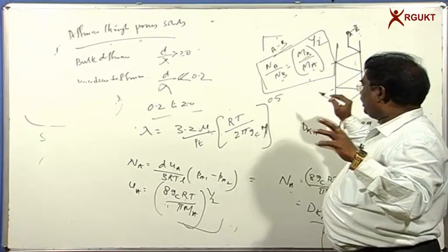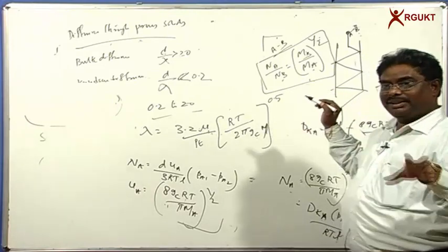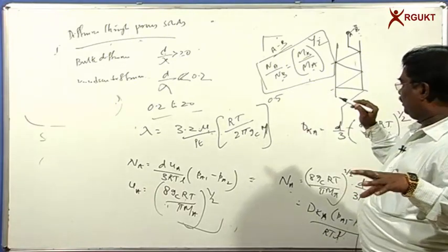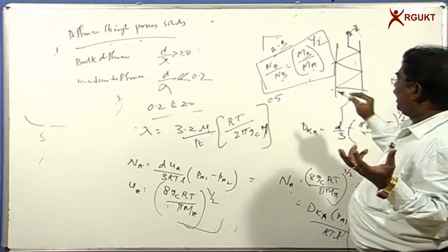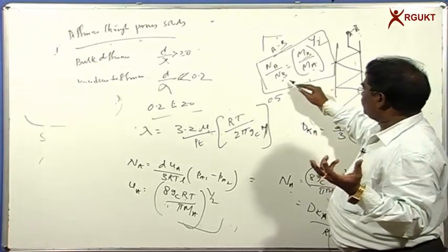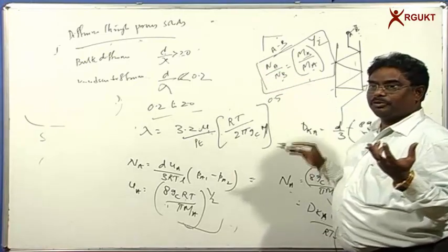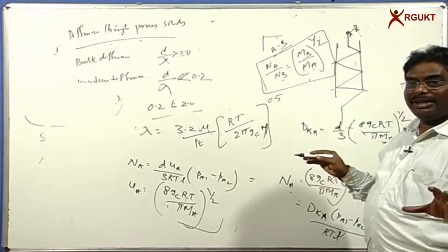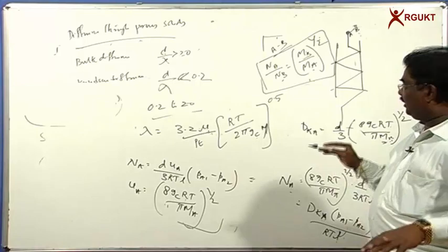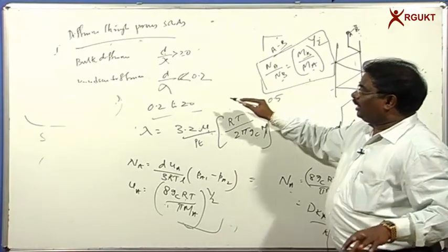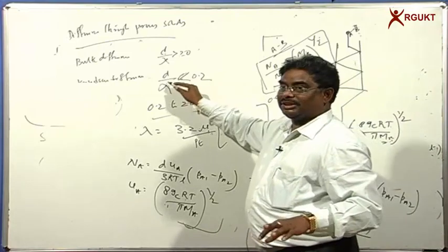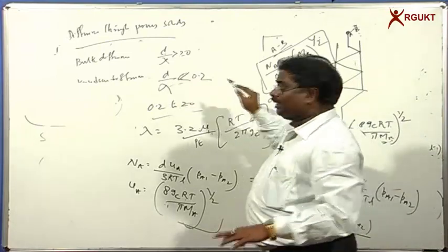Uranium-238 and uranium-235 have the same vapor pressures, but for many applications we need the uranium-235 isotope. To separate it from uranium-238, there is no other mechanism than gas separation using porous membranes, where the diffusion is taking place through Knudsen diffusion.